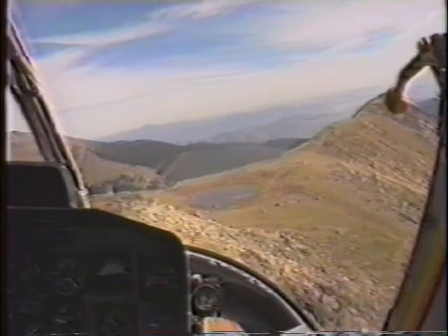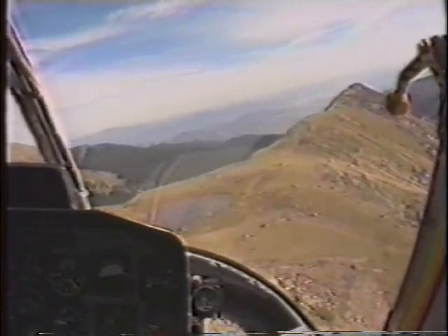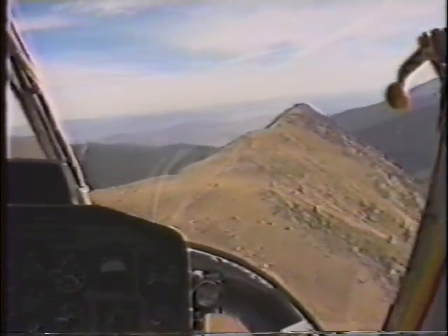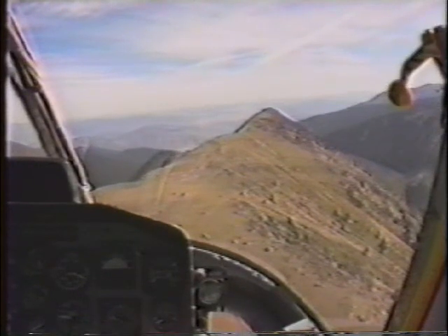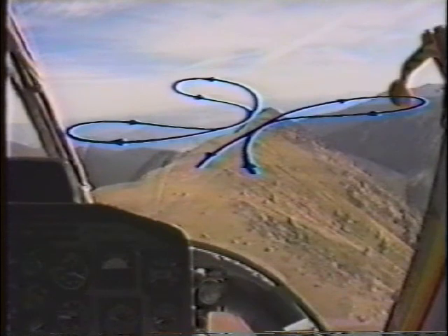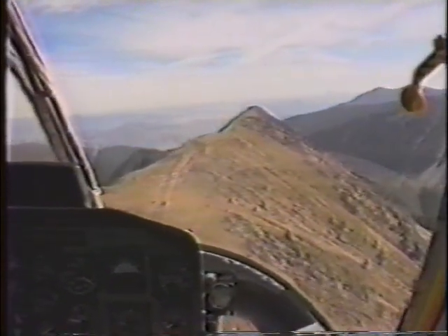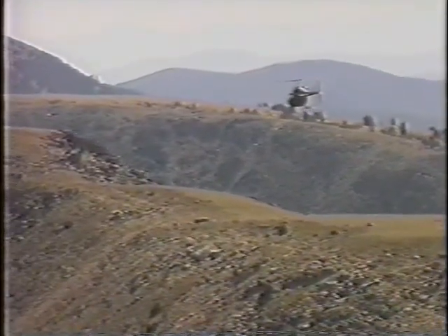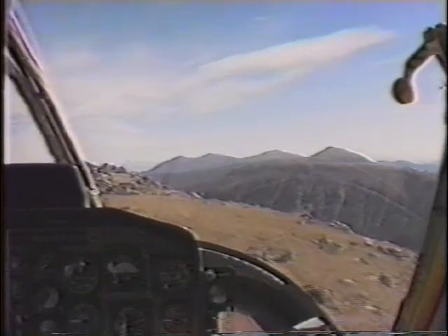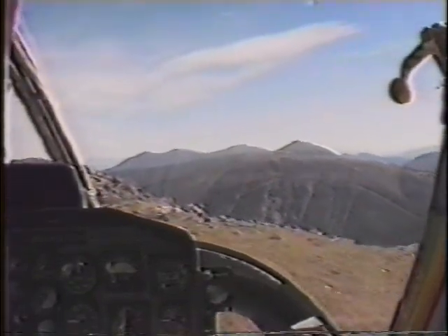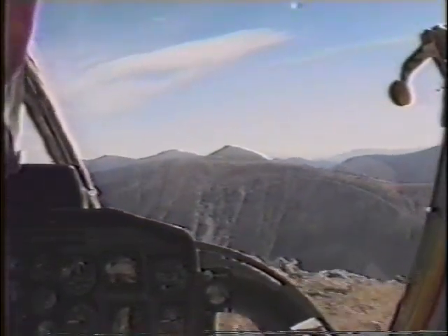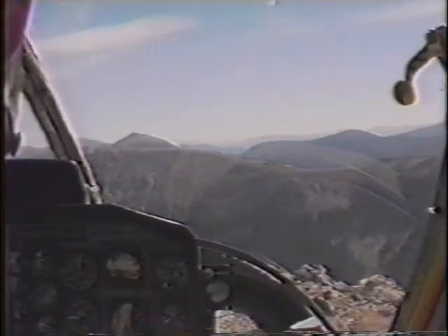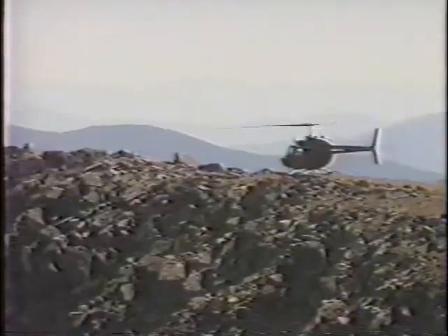With ridges, look for a landing point in the forward edge of the possible area or the highest point if there is one. Keep the aircraft in trim, the crab angle keeping the nose into wind, and look at both sides of the ridge using a figure 8. Ideally, you should try to stay upwind on a ridge, but the topography may force you to approach from the downwind side. If that's the case, find the demarcation line and stay above it out of the bad air. Never turn into the ridgeline and sacrifice your drop-off.